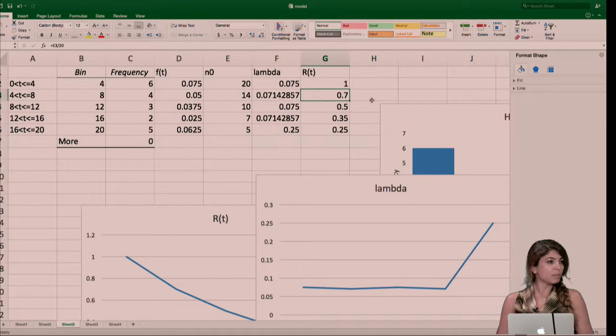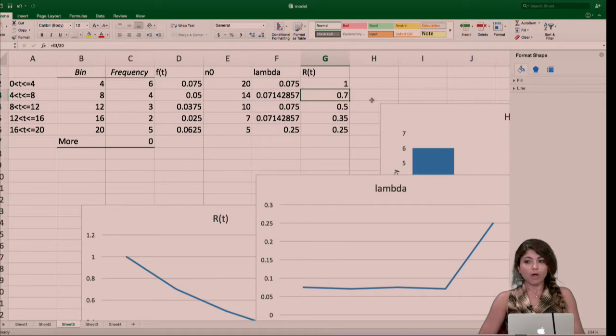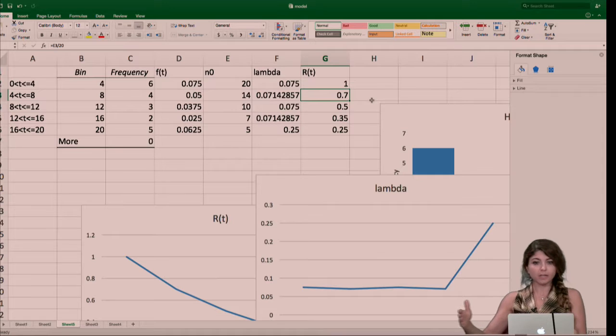Have you heard of design of experiment? No? Okay. So if I want to test the component for its reliability, one thing you have to make sure is that you fix everything else besides what you're testing for. Basically, it means that if I want to see how long this marker is going to work, I have to fix everything in a controlled environment. So there is no difference from testing one component to the next one. I'm not testing the first component in hot and humid and the second one in cold weather. They should be tested in a consistent environment.